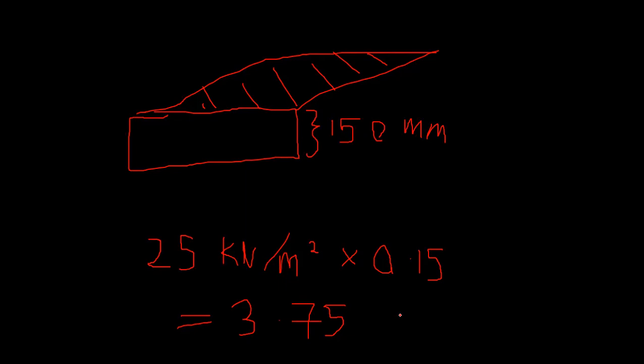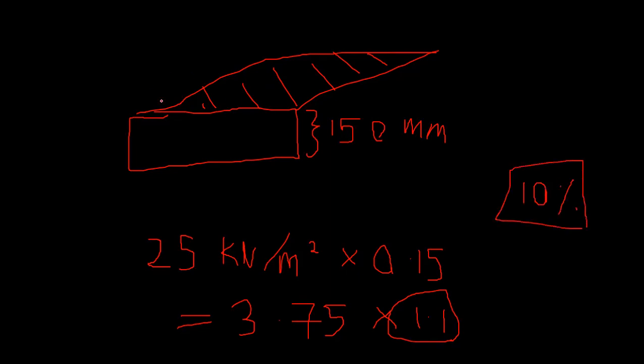Sometimes, to consider beams and everything, people multiply this by 1.1. They consider the beams and columns to be around an additional 10% of the total dead load, so they multiply by 1.1. If you want, you can do this. I'm not going to do it in this example.